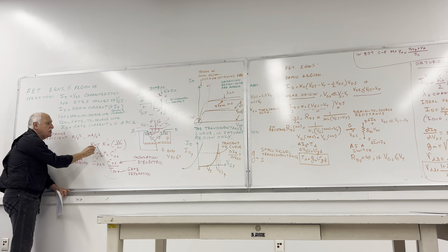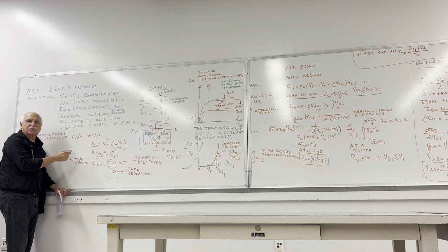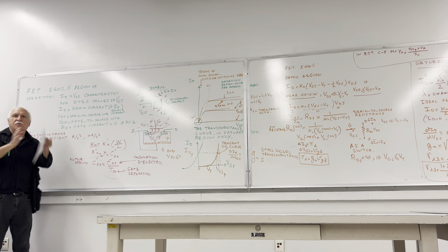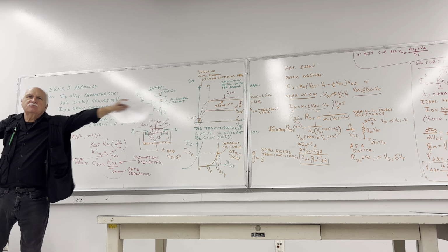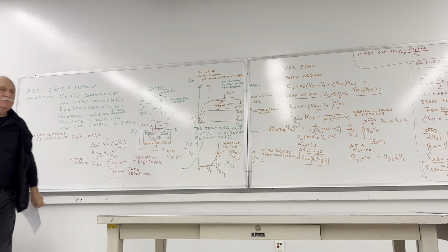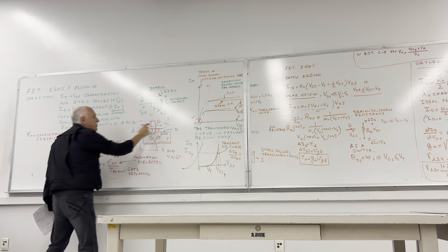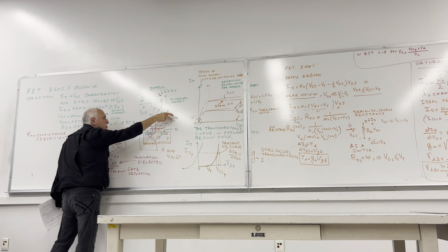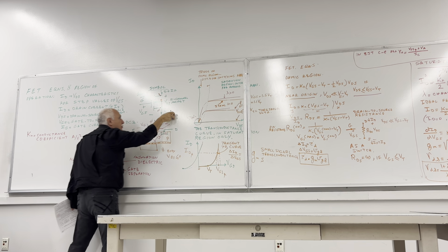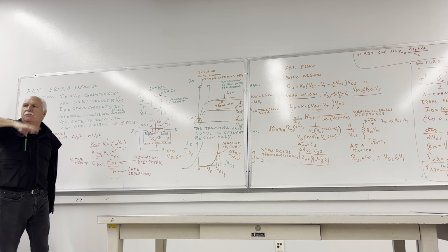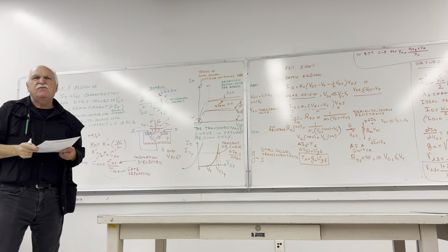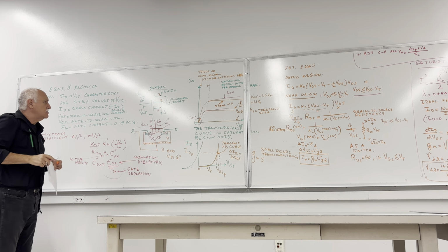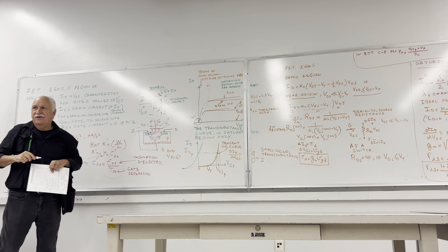Kn can be easily controlled, that's the great thing about the MOSFETs, with the W over L ratio. So if you want to make different gains, just make it wider, make it deeper. It will increase it. You can keep all of them with the same length, and in some places where you need more gain, extend that in a masking operation. It's very, very compatible. I think this is a transistor that will stay forever.